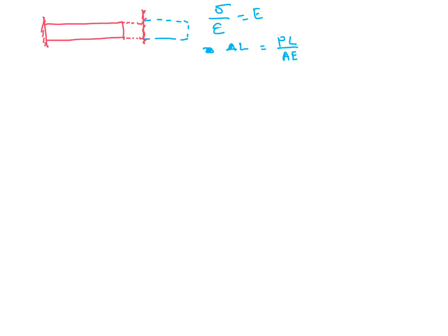Here we will get two stresses, thermal stress and axial stress, or normal stress. This is the gap. If the gap is not available, it will expand like this. So two stresses we will get. First we will check for axial stress. We know stress by strain is E, and our delta L is PL by AE. So delta L, this distance, is 1.5 mm, already given.